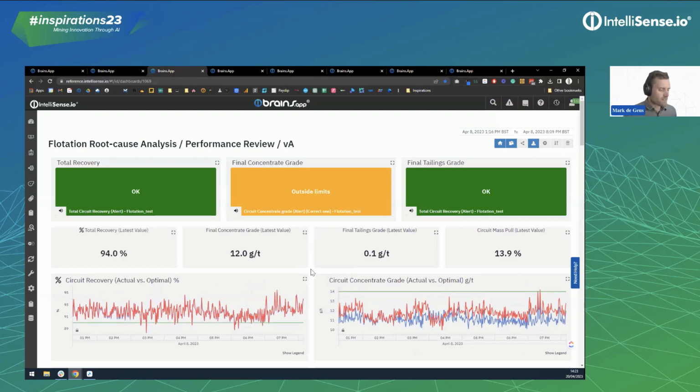In the flotation circuit, one of the hardest parts of flotation is not necessarily the lack of data, but the lack of instrumentation in the right areas to get you the right information. For example, recovery. Recovery is often measured through laboratory, and so is reported about 4 hours after the fact. And so decisions are made not proactively, and so therefore our recovery as a result suffers.